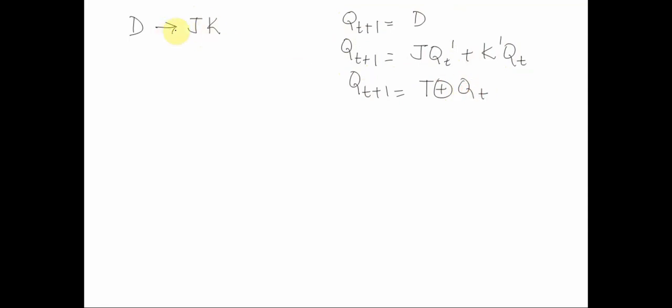When we converted a D flip-flop into a JK flip-flop, we simply said the input D could be supplied equal to J Q' + K' Q. Now let's take another example.